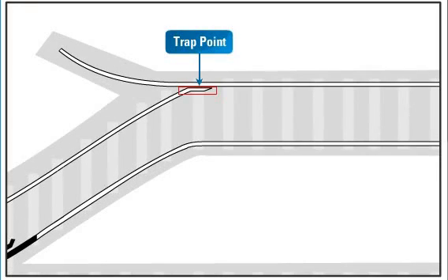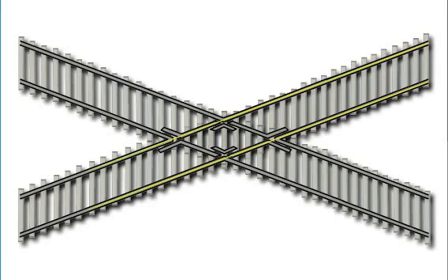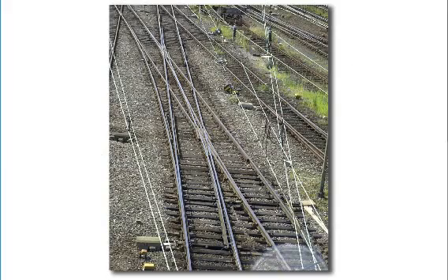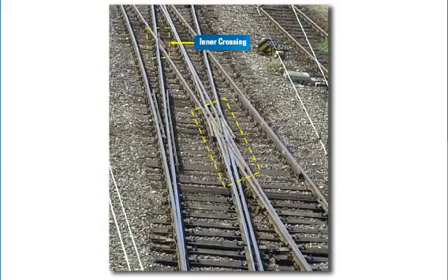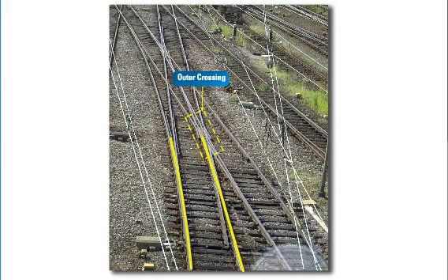This is a single switch point provided on the off side of the yard and is used as a means for isolation. Diamond crossing. This is formed when two tracks cross each other without any connection, permitting only a straight movement. Single slip. In a diamond crossing, when rails are added between the outer crossing, movement around one of the corners is known as single slip.